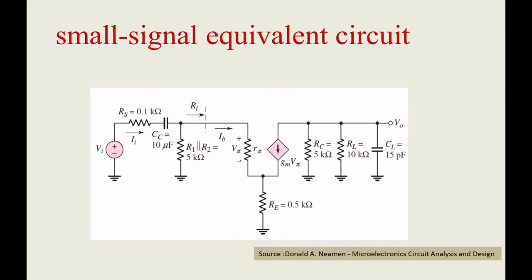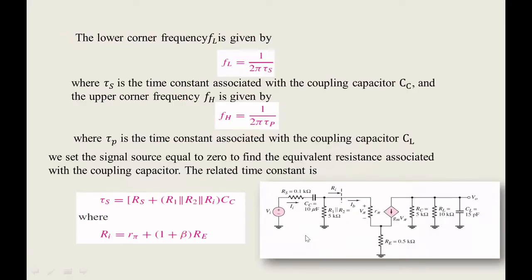You can see here, this is an input coupling capacitor, this is a load capacitor. The corresponding resistances are in parallel. Here, in the series capacitor, these resistances are in parallel and this resistance is in series with this capacitor. Right, so that is very important. That is the idea I want you to get. Now let me erase this. Okay, so now a very interesting part.